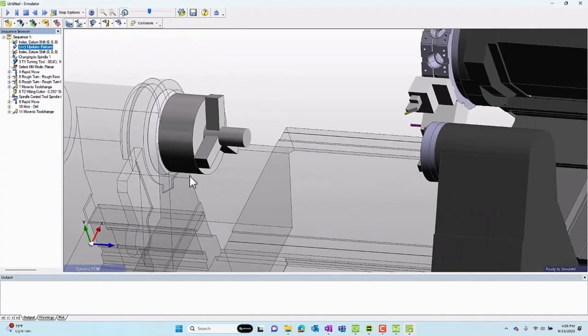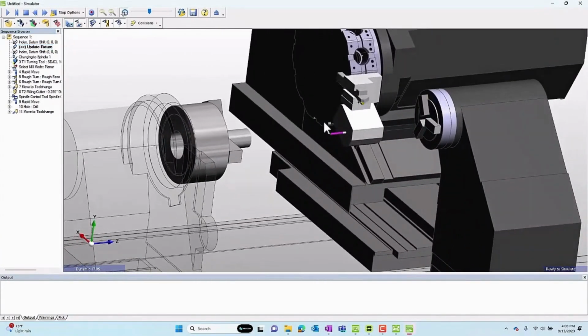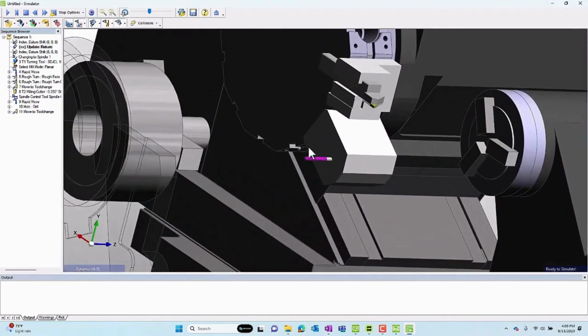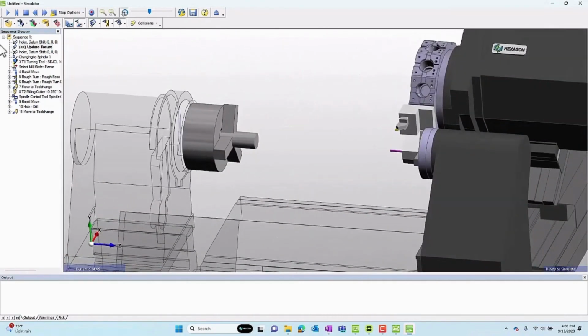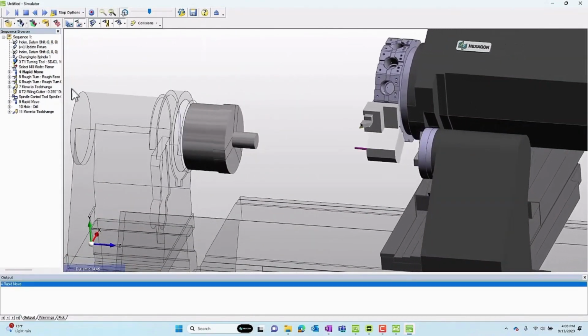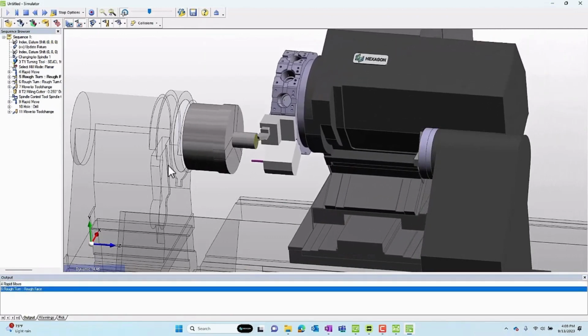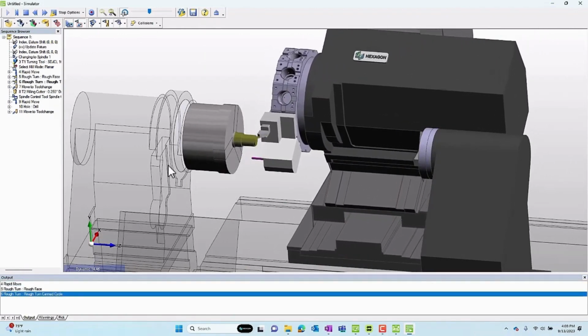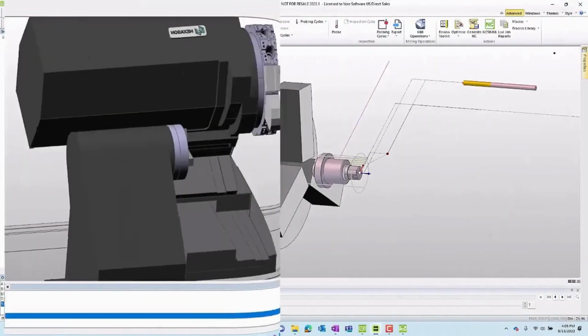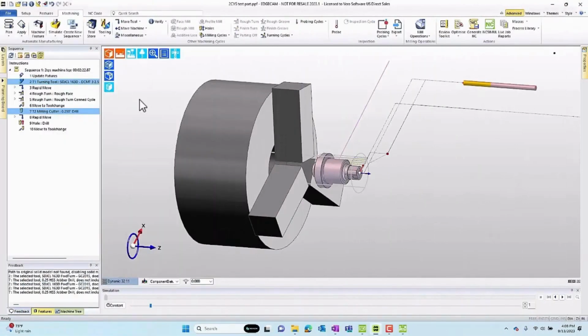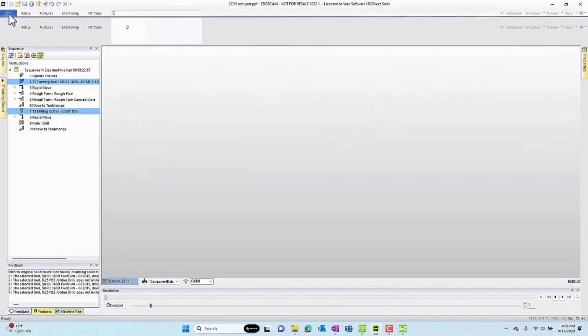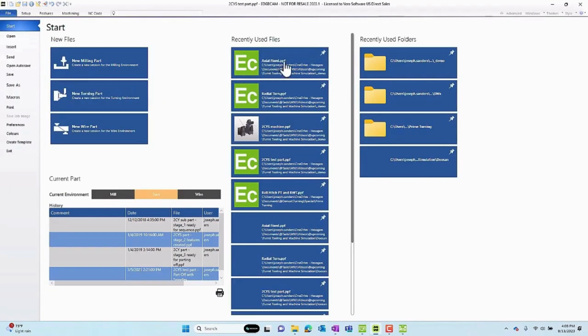When we go to simulation and have a look, we not only see the blocks, but now the tools are in the correct position within those blocks. Again, the values are taken from the mounting position at the center hole. So center hole to tool tip edge in Z and X is what we need to know. Well, how did we know those values? Let's go have a look at that now.